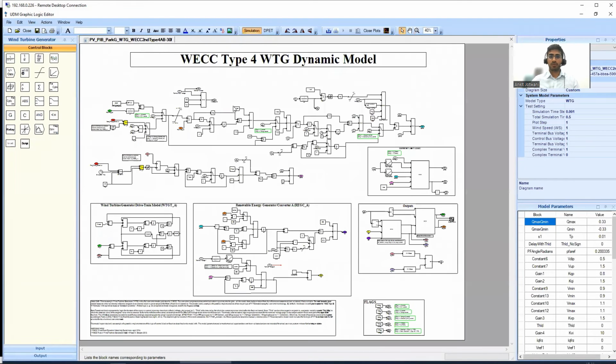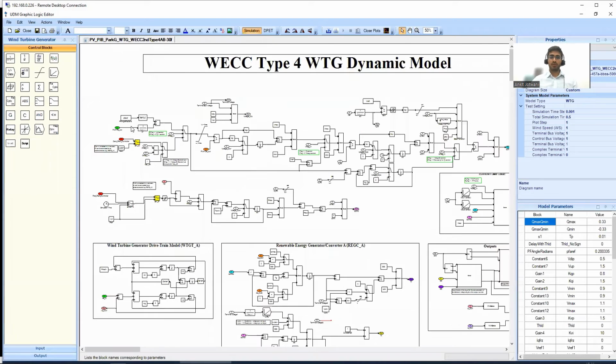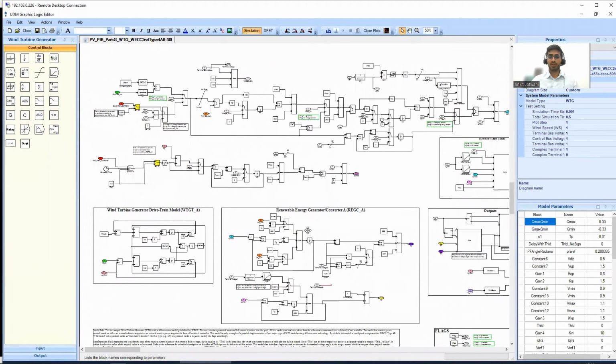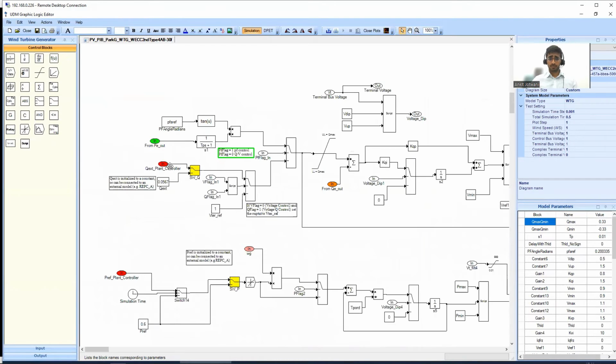So this is the VEC model. We have the reference generation, then the electrical control block, then the generation and converter block before we send the final references to the end element. The references are generated from the plant controller model, which is in the lumped load element, and that's why you see the switches linking to the references from the plant controller.